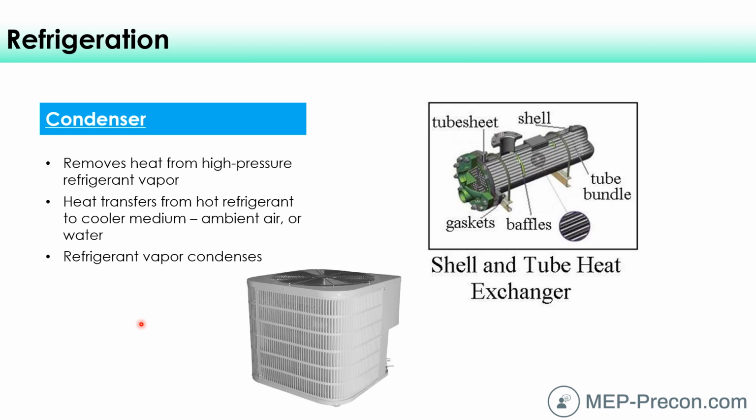That's our evaporator coil. So the BTUs from that room are going to jump into that evaporator, and it's going to come outside to our condensing unit. And if you've ever walked by here and put your hand over it when it's running, you feel that heat on it. And without knowing the refrigeration cycle, you might say, boy, I don't know what this machine is, but boy, it sure produces a lot of heat.